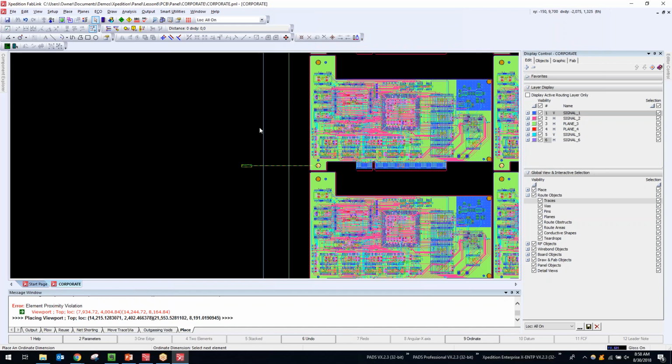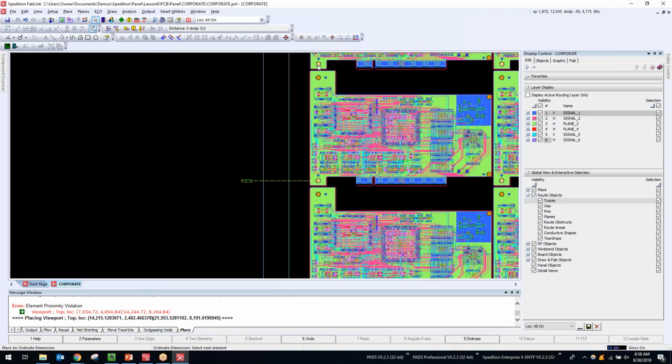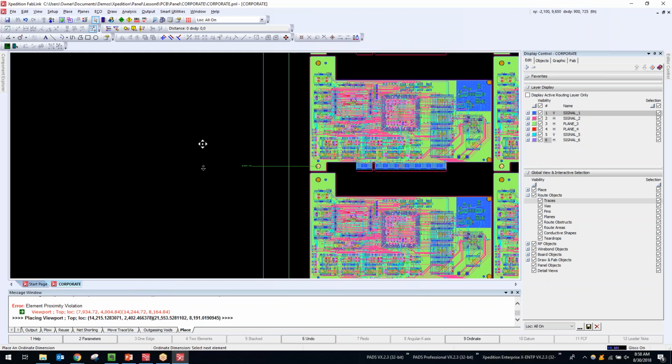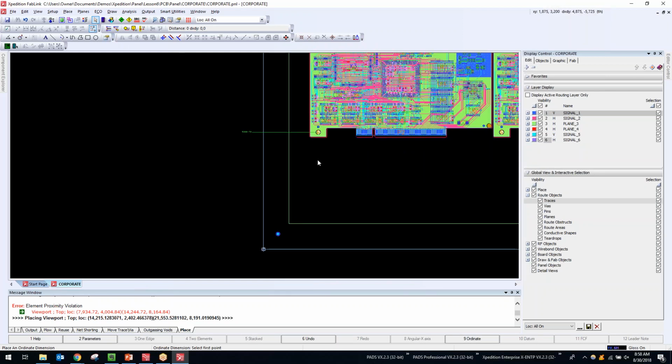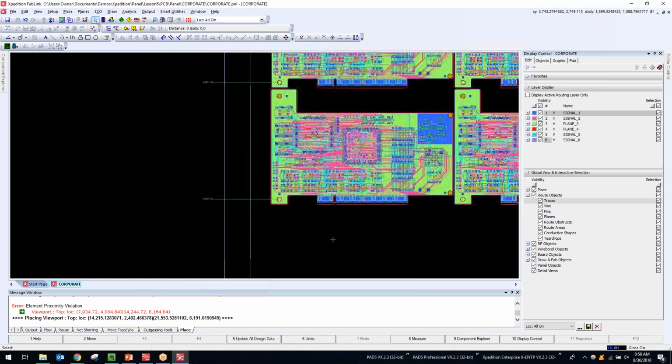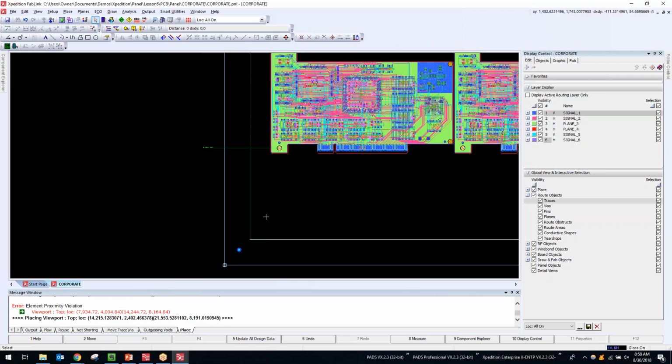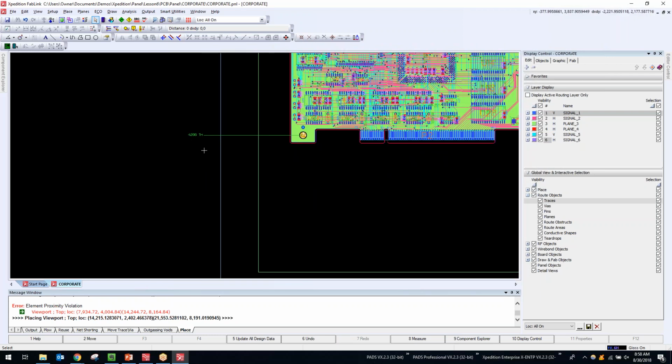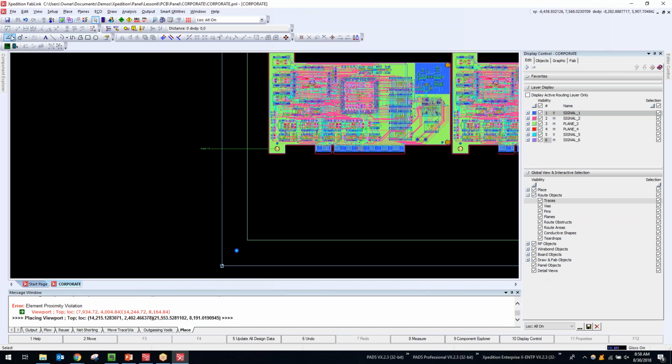that origin. So you'll see as soon as I click on objects, it mirrors that scheme of how far that ordinate dimension is pulled off of that mounting hole. Okay, so that is ordinate dimensions. And again, these are real-time ordinate dimensions. If I update the origin for whatever reason, these dimensions will update as well.